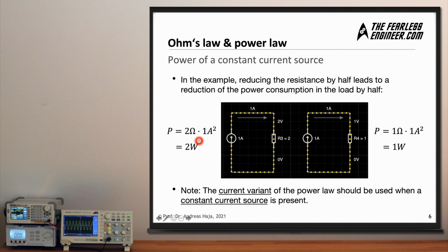If you do not know how your circuit will behave, because let's say you are powering it with a solar cell and you do not know that much about the behavior of the solar cell, you might need to take a look at the current voltage characteristic of this cell to make sure that you use the correct forms here, and then you can assume a certain behavior of your power source which you build into your circuit, which is powering your circuit.